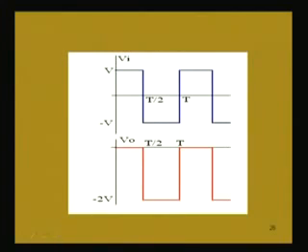So, we get this voltage. Here you can see that the voltage waveform given was this one, but now we are getting a waveform where the DC level is clamped at a different voltage. We are getting minus 2V, earlier it was minus V. So, the waveform is clamped at a higher voltage. This is an example of a clamper circuit.